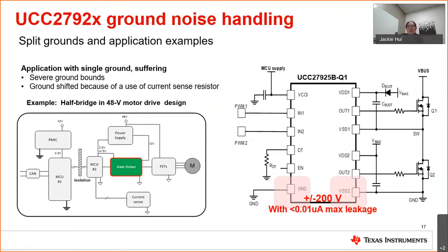You can pretty much view it as two isolated, separate grounds. So it allows you to route your ground with a good layout, really separating your input signal ground and your system ground, to reduce the impact of ground noise creeping back into the input of the driver.